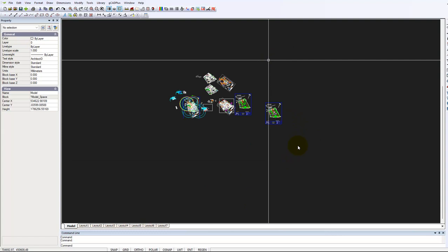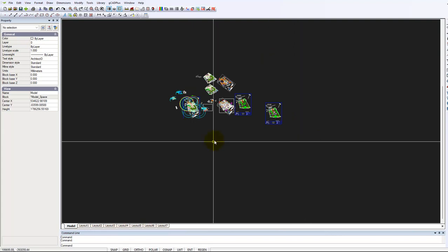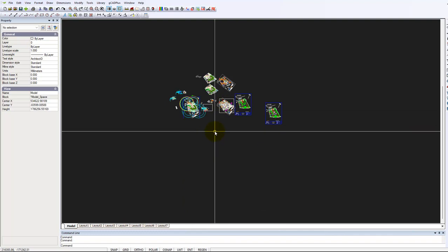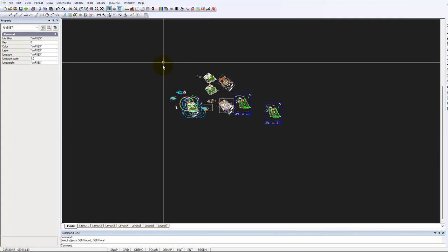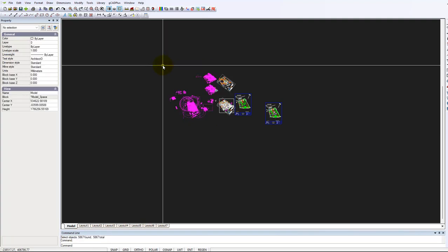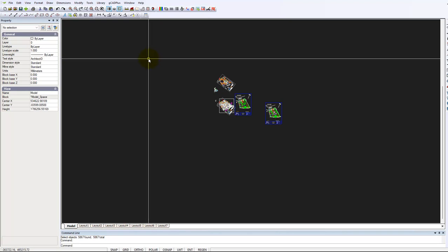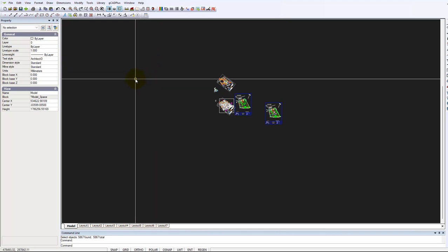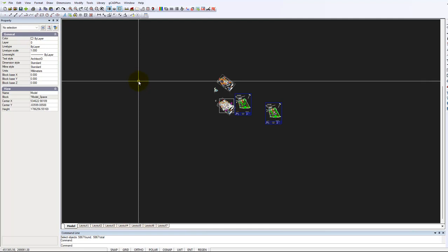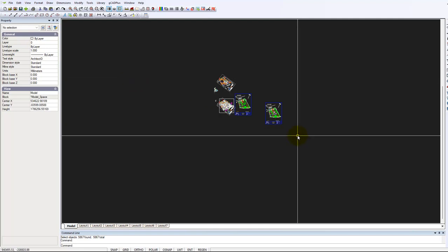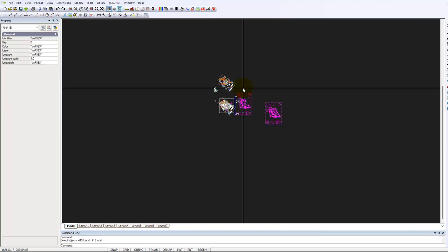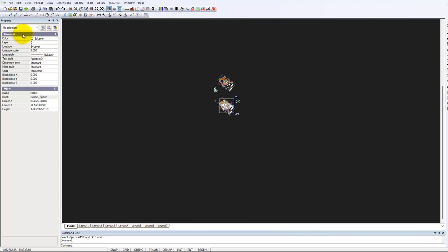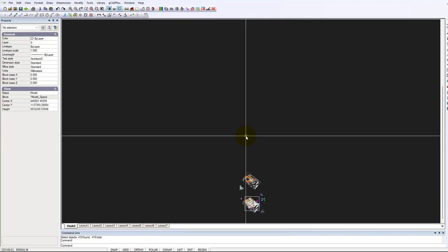And I'll start removing. Remember, this is the area we're interested in. So let's see if we can set a crossing window up and delete those entities. What I'm looking for is a substantial change in the performance of this particular drawing file. And I think we can get rid of these as well. At this point, I'll probably save the drawing and zoom extents again. There's still something outside here.